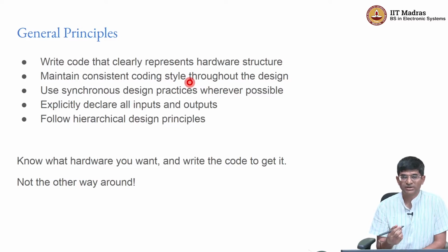There are also other kinds of conventions where sometimes people require things like anything that is actually supposed to become a hardware register should be named with perhaps _R or _Q as part of its name. Now, these are again conventions depending on where you are finally writing your code, and if you are working as part of a larger group, the group might have certain conventions associated with it. So I don't want to really establish and say, okay, this is the only way you can write code, although I will be showing certain examples where perhaps things that potentially are nice to follow.